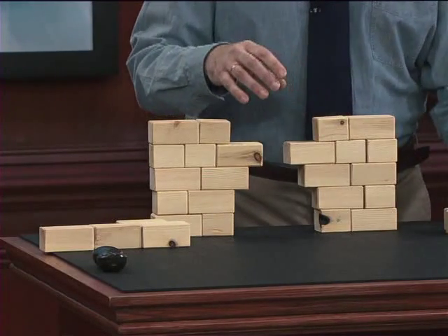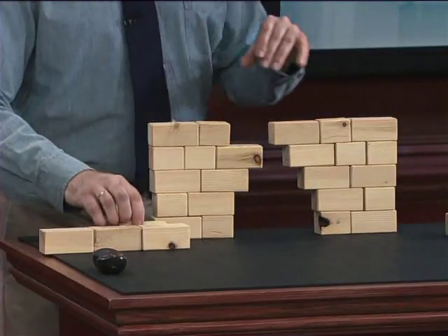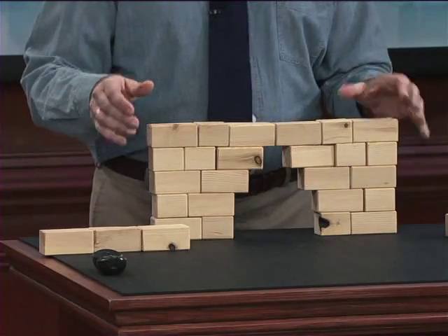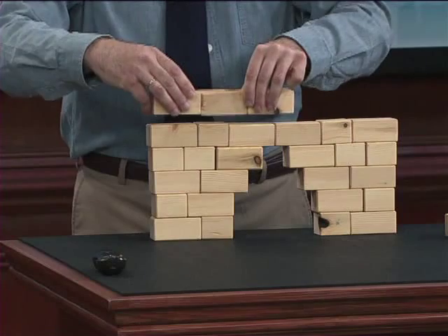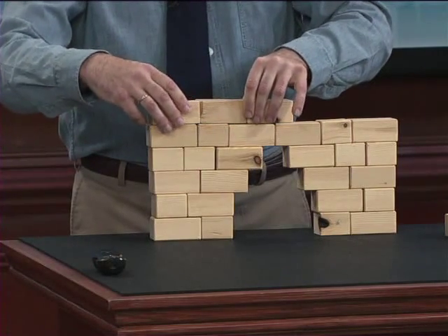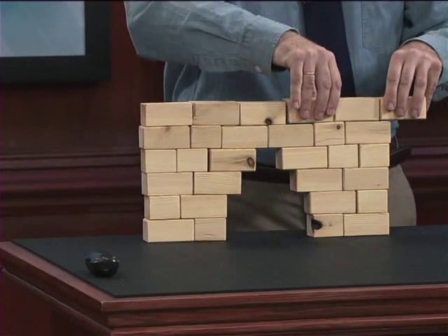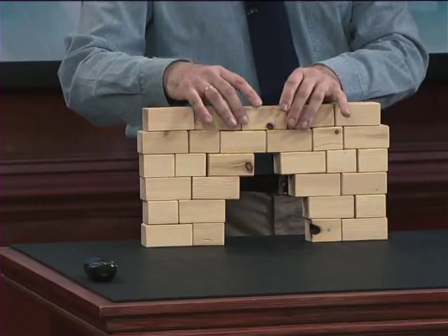Now we'll add another stone here. And finally, we're in the position of closing the arch at the top. And in order to stabilize it just a bit more, we'll add one more layer or course of masonry beyond that, bridging across the gap, and the same from the opposite side to create the complete corbelled arch construction.